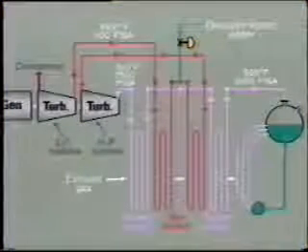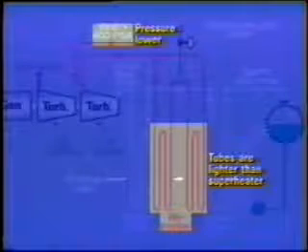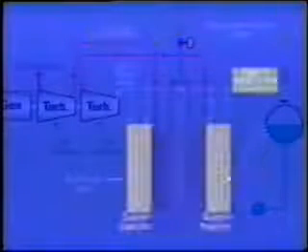The reheater tubes are lighter in construction than the superheater because the internal pressure is much lower, usually about 400 psi, say 28.5 bar, as compared with, say, 1500 psi or about 100 bar for the superheater.